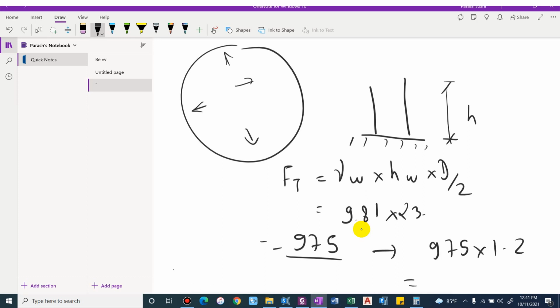Depending upon the horizontal seismic coefficient, you can take either 0.2 or 0.1. For Nepal, generally the horizontal seismic coefficient, this is for the stability case, so the dynamic effect will be 0.2. Basically this is 2/3 of PGA, and considering PGA as 0.3, we get 0.2.